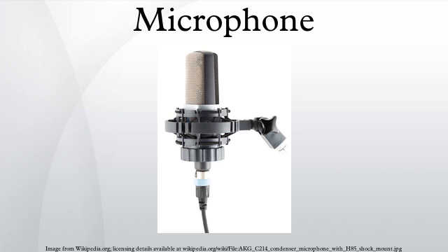Some microphone manufacturers state the noise level using ITU 468 noise weighting, which more accurately represents the way we hear noise, but gives a figure some 11 to 14 decibels higher. A quiet microphone typically measures 20 dB SPL or 32 dB SPL 468 weighted. Very quiet microphones have existed for years for special applications, such as the B&K 4179, with a noise level around 0 dB SPL.